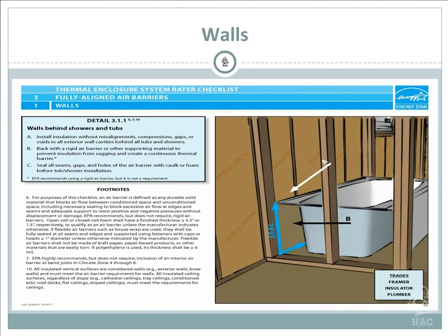Again, you can put rigid board back there, something just to hold that in place, or you can seal it with rigid board if you want. Some people use rigid board in case it ever gets wet. Again, you want to seal all gaps, seams, and holes on that rigid board or the outside.